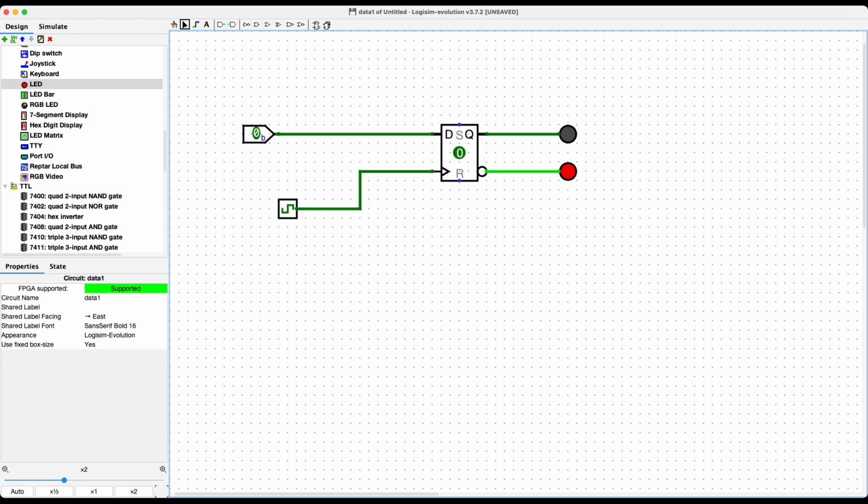All right, now, watch what happens to the output if I flip the input to a 1. When did the switch happen? The instant that the clock went from off to on. That's called the rising edge, namely this part. Let me demonstrate this again. All right, so let me turn this off.